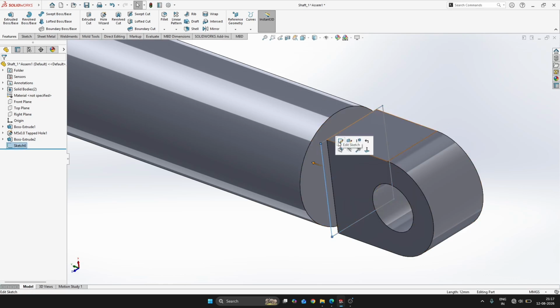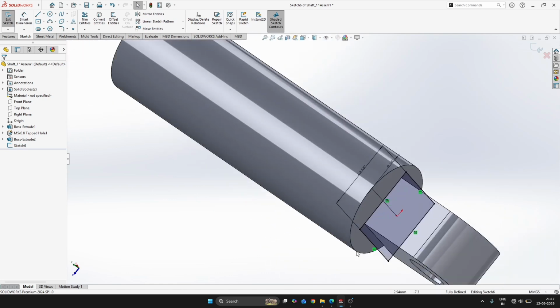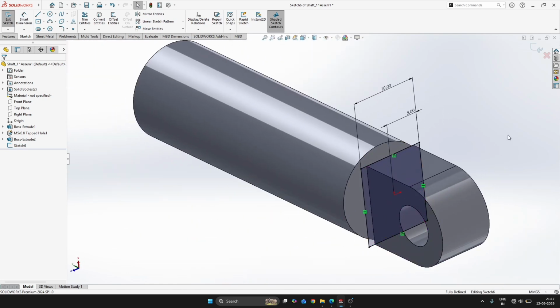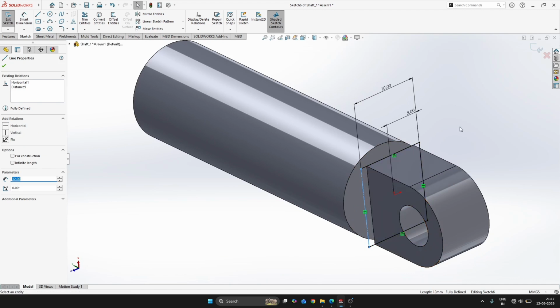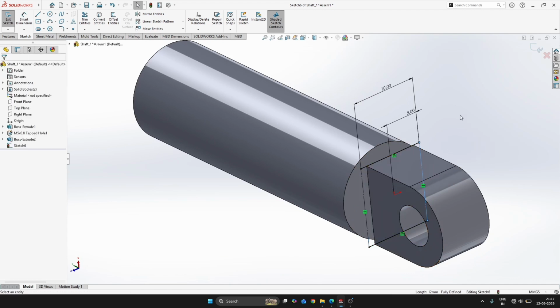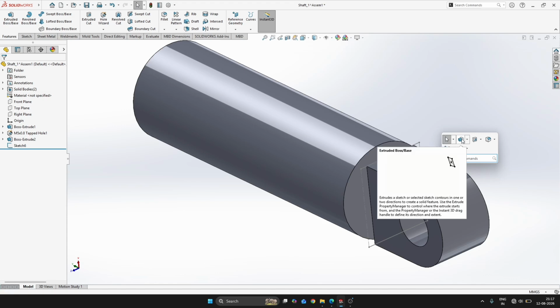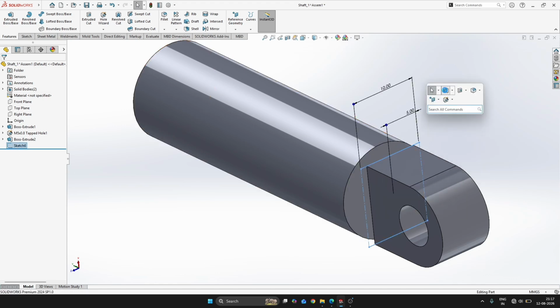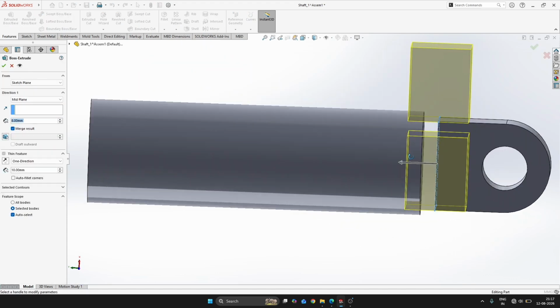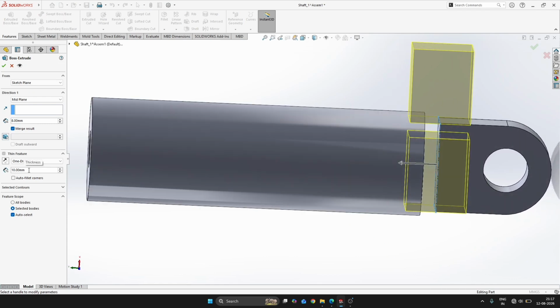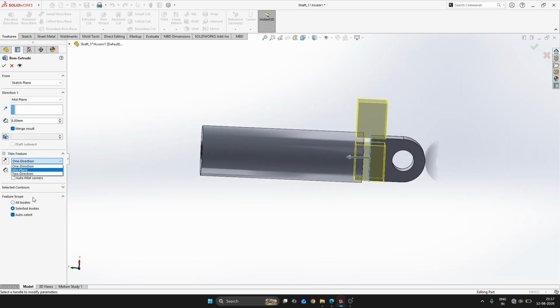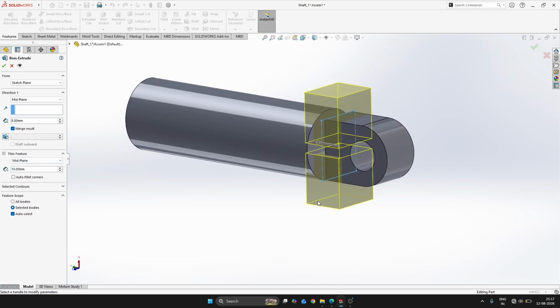Yeah, what I will do is make it into construction. Exit. Select the sketch, extrude, and the thin feature is turned on. Okay, we'll have to use that. I think mid plane. Okay, 10 mm, we can't use 1 mm.